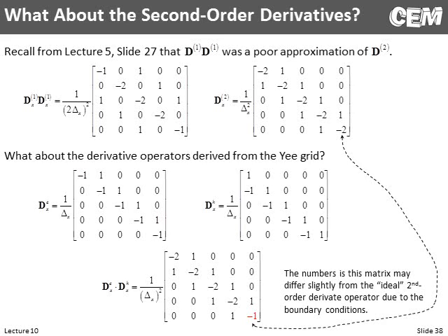So this top row is what happened before when we multiplied two of our first-order derivatives together. And we see that this is a correct finite difference formulation. However, we're reaching farther out into the grid. See, there's a 0 between the -2 and the 1s. We're reaching way across the grid, and we're losing a lot of resolution. It should look like this, which is what we constructed manually.